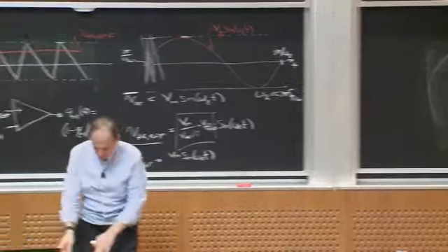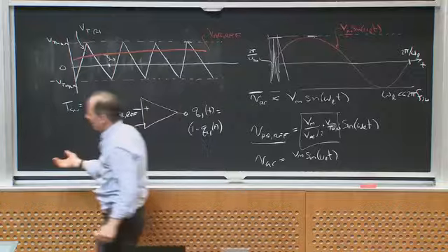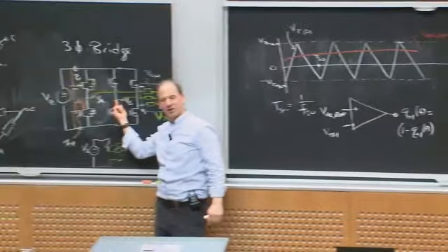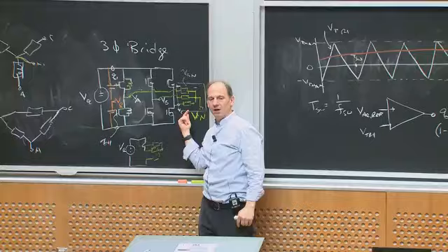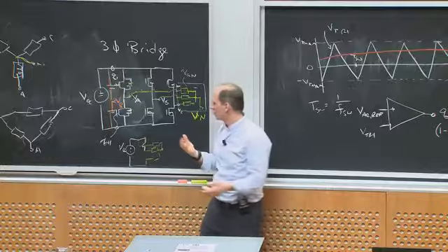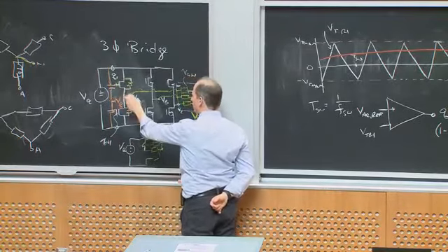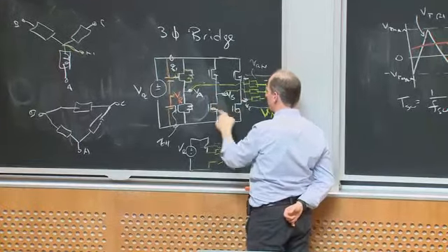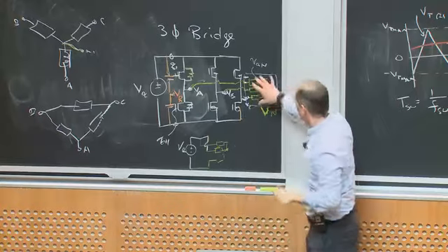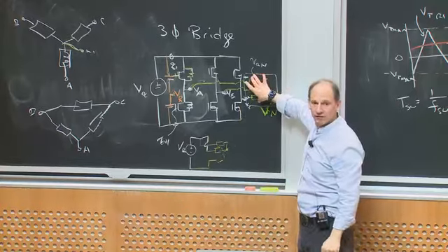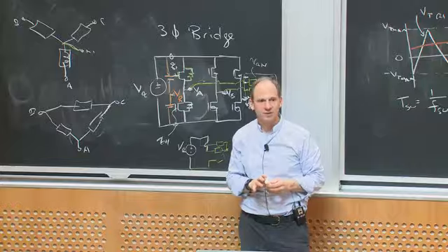So when we do this for phase A, I do the same thing for phase B, except shifted by 1/3 of a line cycle, and phase C is shifted by 1/3 of a line cycle. Then, at least as far as the local averages, I'm creating a voltage A with respect to reference that follows a sine wave, a voltage B that follows a sine wave, and voltage C that follows a sine wave. And yes, each of these nodes is PWMing up and down, but if this load is inductive, it will filter that, and then the currents will look very sinusoidal. Does that make sense to everybody?